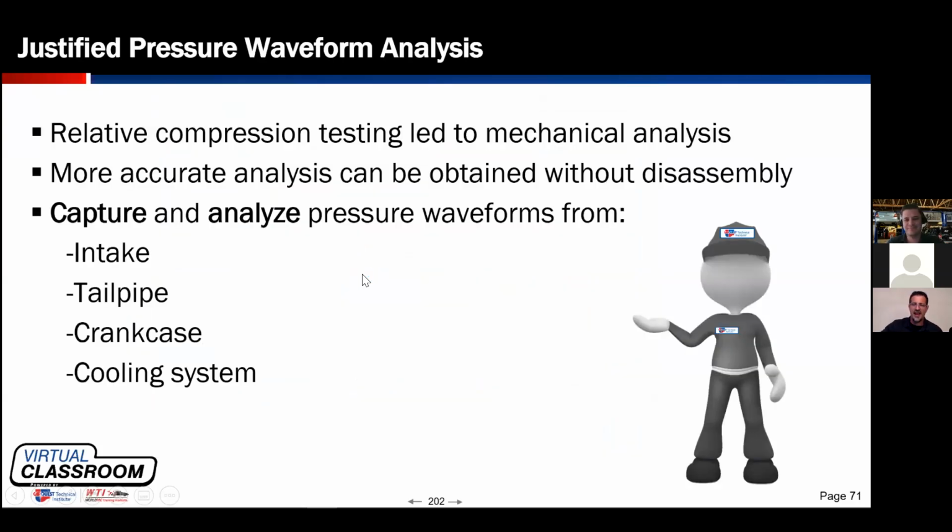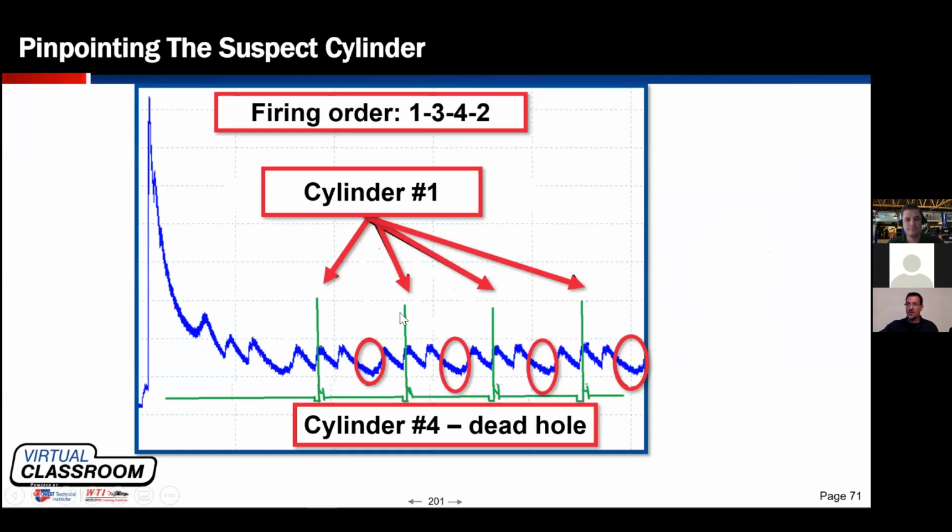So it's that generalized testing that's going to lead us to the pressure waveform analysis, because the pressure waveform analysis is a bit more involved. But think about it this way. If I already know I have a mechanical problem, doesn't it make sense that even if I invest more time grabbing my pressure transducers and researching a firing order, that I'm definitely going to see more information? I know I'm on the right track. Please raise your hands if you agree with that line of thought. Good, then you're right with me.